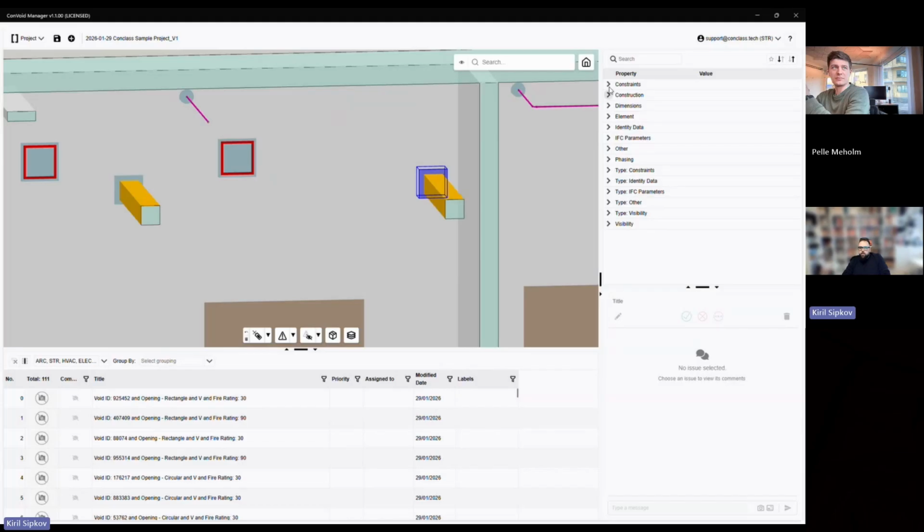What I would like to do here is to check the openings which are placed in in situ concrete walls. So basically, I'll check in which parameter that information is hosted. In this case, it's in Construction: Construction Material of Host, in situ concrete.